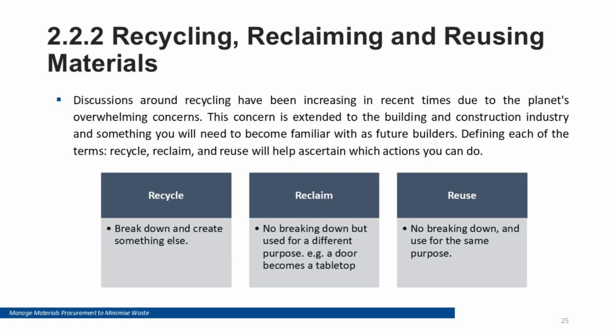Recycling, reclaiming, and reuse are key to reducing landfill. Reuse keeps materials in service with minimal processing. Reclaiming recovers materials so they can be processed again, such as salvaged fixtures or recovered timber. Recycling transforms materials into new products, such as metals or crushed concrete. To make these options work, the site needs separation at source, clean storage, and clear pathways to approved facilities or reuse locations.